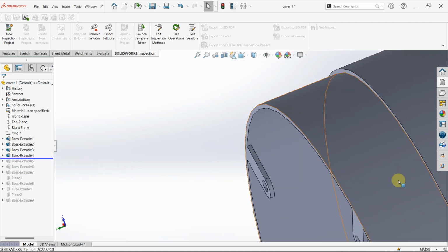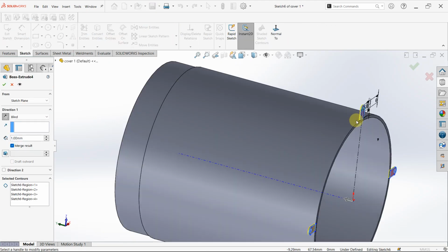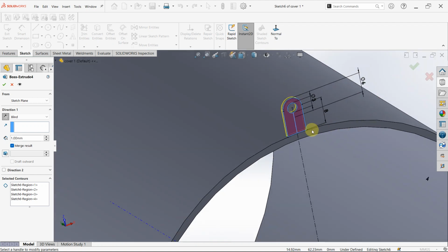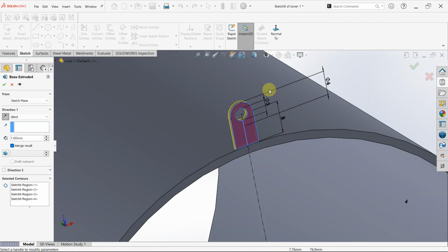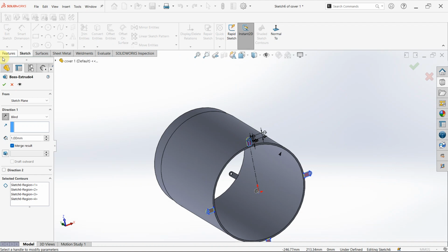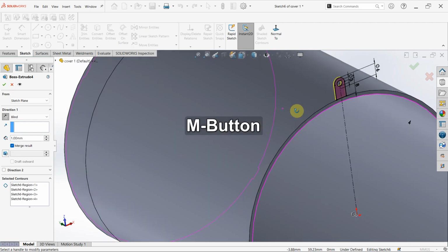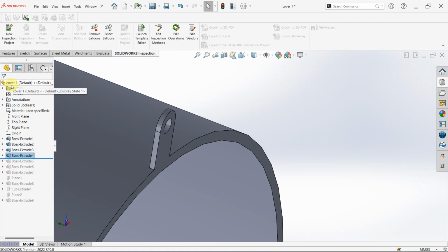And then the next, okay, this back side, a similar method for a different position. This is the sketch. On this, from the middle to there is 8 mm, 3 mm diameter, and the arc of this slot is 6 mm. Then you use circular sketch pattern also. Then extrude up to 1 mm and merge it. See the direction on this surface. This is the sketch surface, downward.